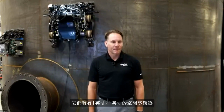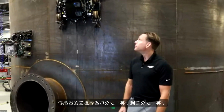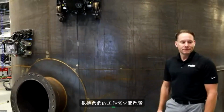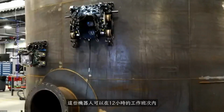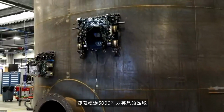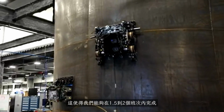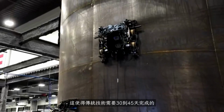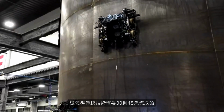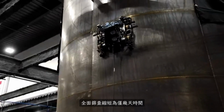They have 1 inch by 1 inch space transducers. The transducers are about a 1/4 inch to 3/8 in diameter, depending on the work that we will be doing with them. These robots can cover up to 5,000 square feet or more in a 12-hour work shift. That gives us the ability to do about a 100-foot diameter tank in 1.5 to 2 shifts, bringing that typical 30 to 45 day complete screen with the older type of technologies down to just a few days.